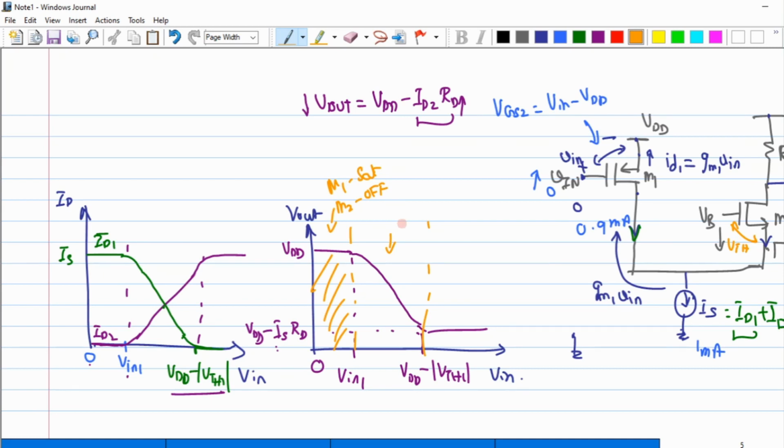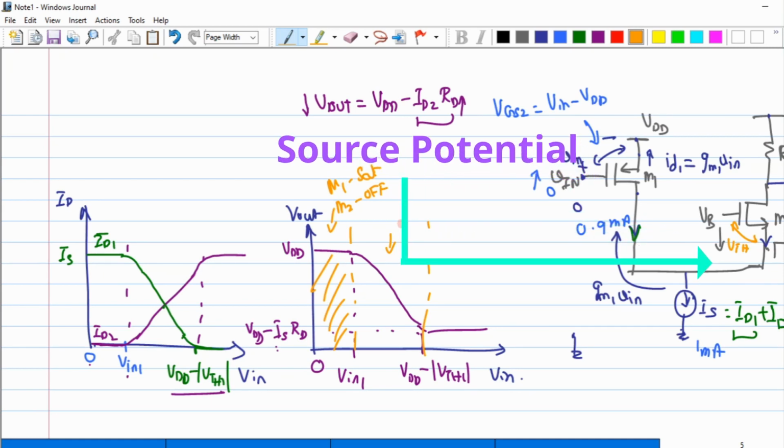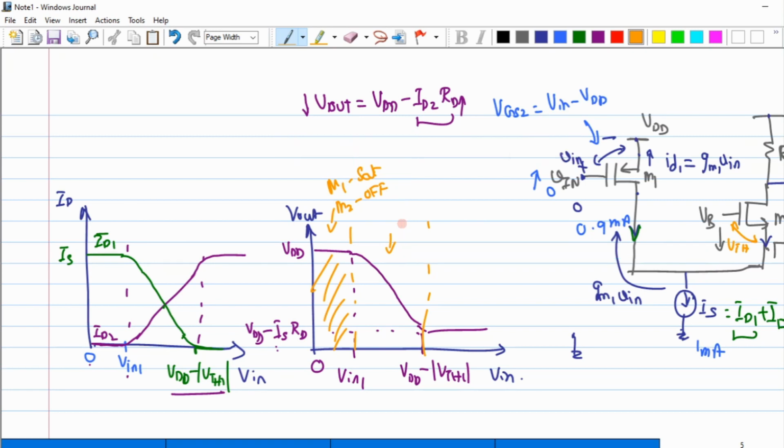It becomes difficult, right? Because I don't know what is my source potential. Without that, it becomes pretty difficult for us to really say anything about my M1 transistor situation. But still, we can think about it. How will I read this potential, the node X potential? When there is no current, what is the value that I would get out of this node Vx? I have a fixed potential Vb, and no current has to flow means the VGS of this device has to be equal to Vt. So, how will I read this voltage in terms of Vb?